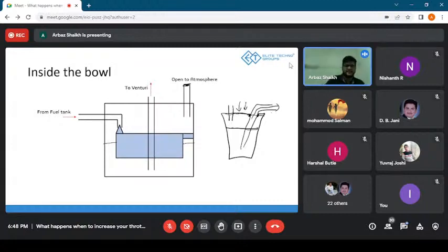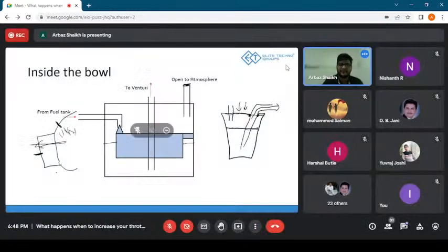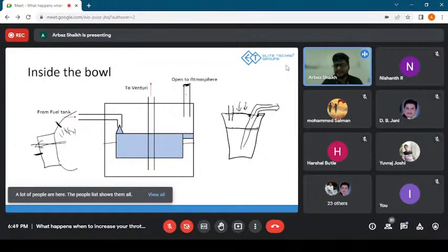You can do this experiment. People have done this experiment on YouTube. Take a bottle cap and make a very, very small hole in it with a very sharp object like a needle, and tightly pack the bottle. If you tightly pack the bottle, no liquid would fall out from this hole because there is no air entering. But as soon as you make one more hole over here, the liquid would flow because there will be atmospheric air coming in. This is what would happen if I close the opening to the atmosphere.